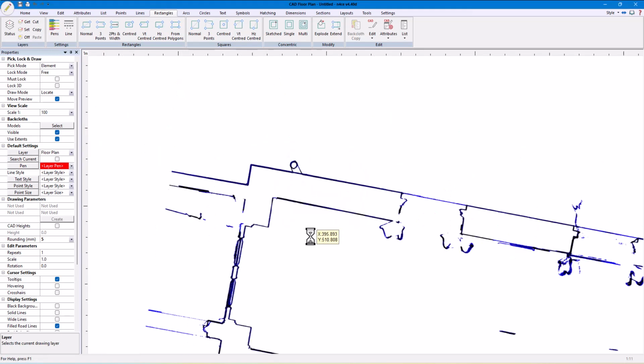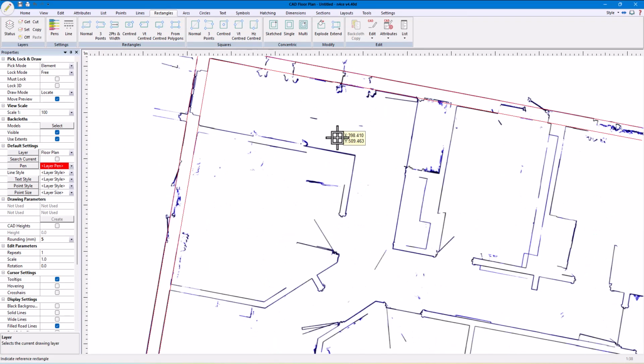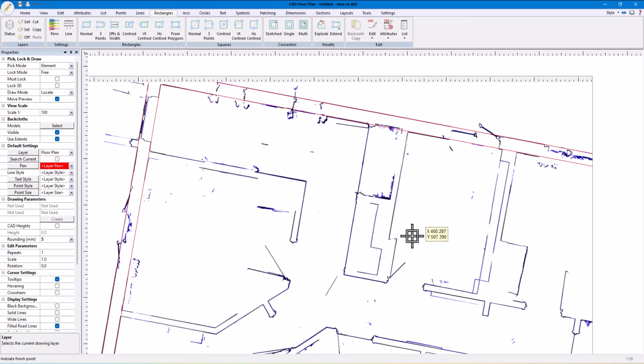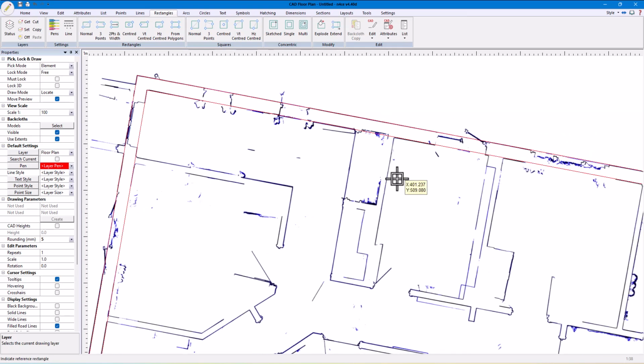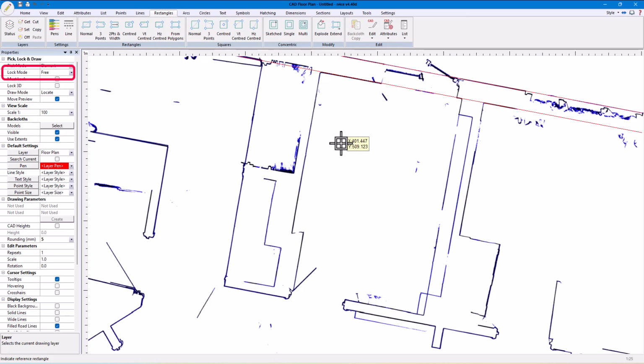Now we will make use of the Gap Extrude tool. This works by first selecting the segment to insert the extruded gap into, then where to start and end the extrusion. Note, lock modes are honored during this process. This is very important as it makes the tool both very powerful, but at the same time, easy to make mistakes.